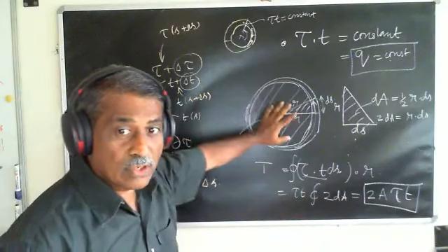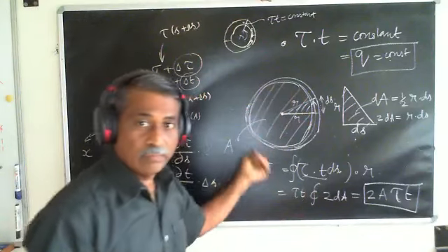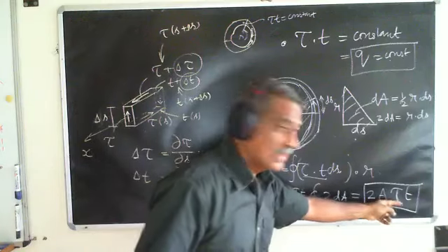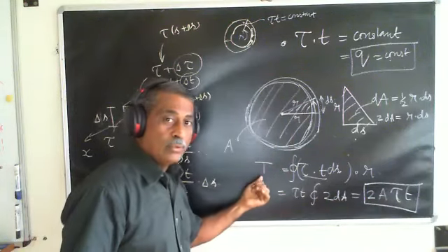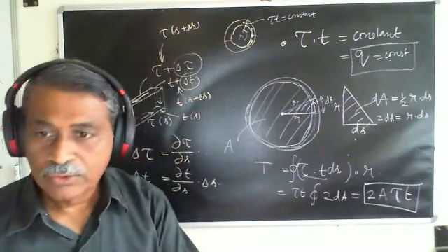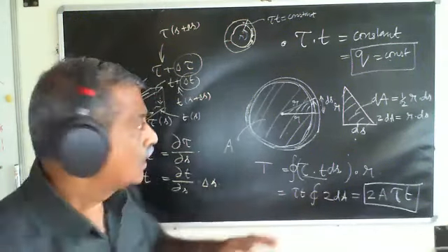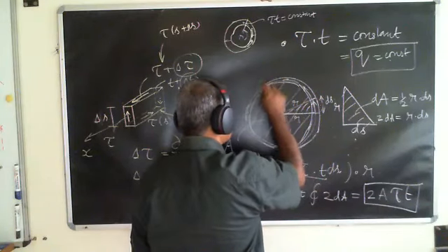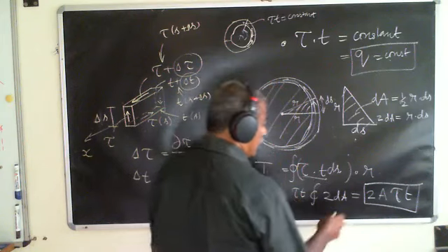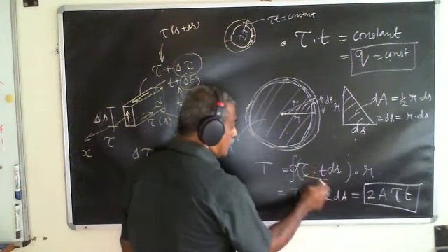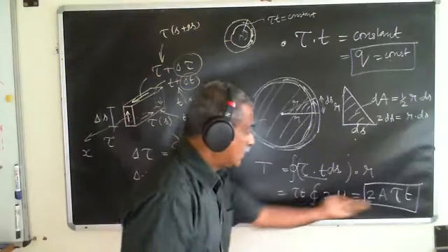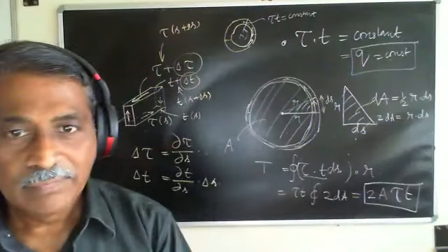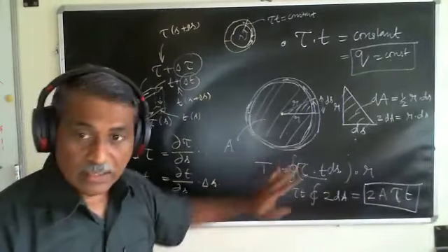I have now solved for the relationship between the stress that is produced due to a twisting moment T. So far, okay. And what did I use here? I said, okay, there is a shear flow that is occurring like this, right? And it helped me in terms of taking this tau times T out so that it is easily found out to be this way. So far, okay. That's the beauty of this derivation.